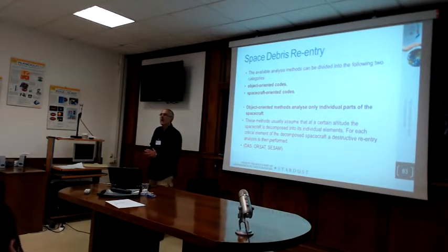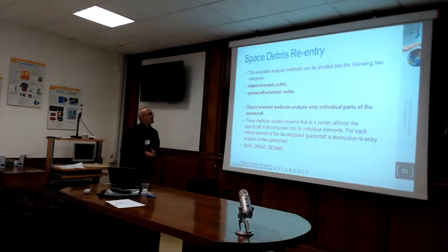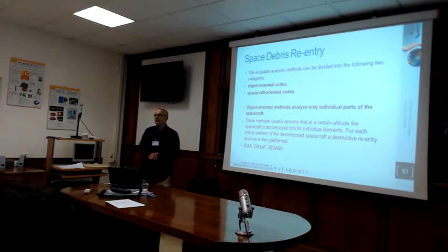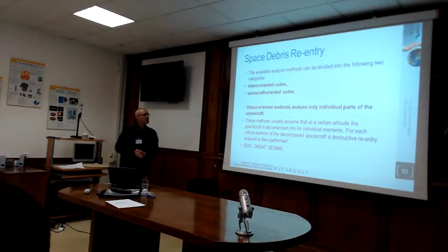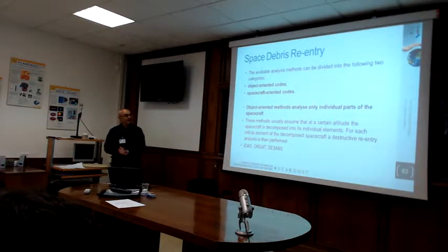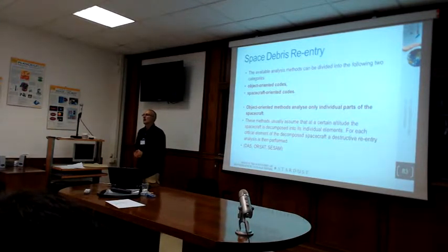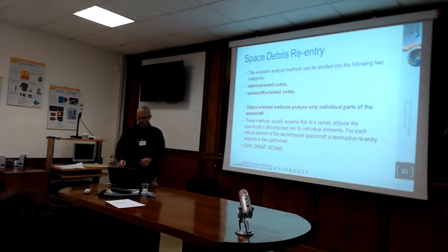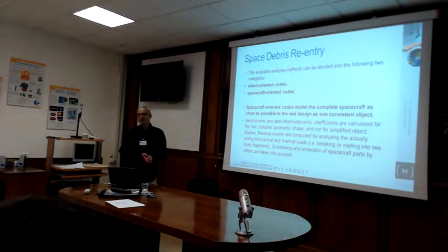Most of the tools are object-oriented, and basically the spacecraft is decomposed in a few elementary elements. This decomposition is done at a certain predefined altitude, and then each element is followed on its own during the trajectory with analysis of ablation, mostly ablation. And then there is the spacecraft-oriented approach.